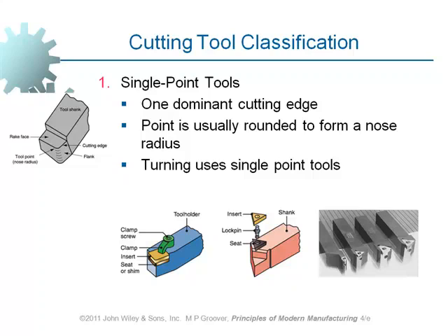By the way, if there is a very sharp cutting edge, which is cutting the material, what we produce would be a rougher surface instead of a smoother surface. And that's something that you will be experimenting in the lab. Those who do the surface roughness test on the lathe, they have got to make use of two different nose radii in order to make a comparison between the two. And you will realize that the one which has got a larger nose radius produces a better surface finish.